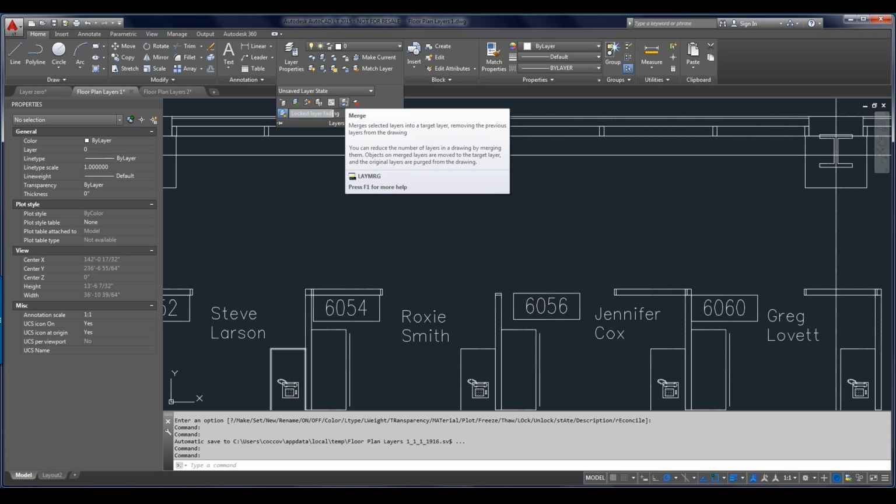Right. The other thing with individual objects, and you covered this in a previous webinar, is you can create blocks, and as part of your block library, you can determine when you drag and drop it from that palette that it automatically goes to a certain layer or a certain color. But that's for individual objects and not necessarily XREFs. So it's a good wish list item, but not at this time.